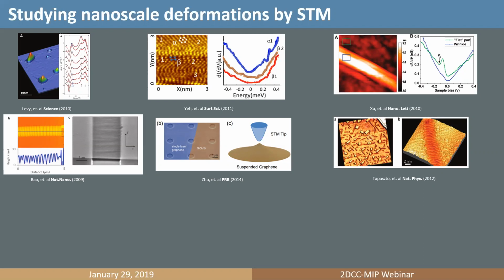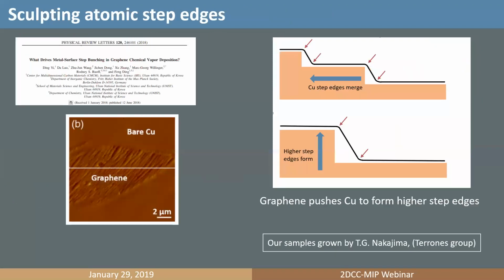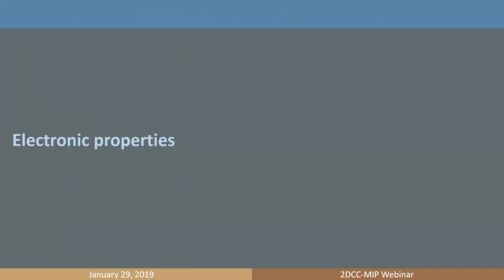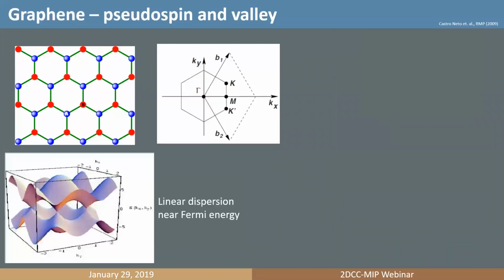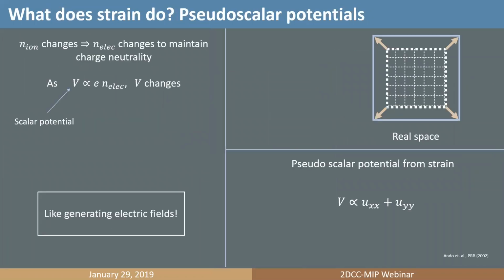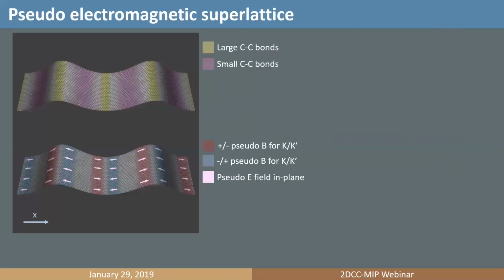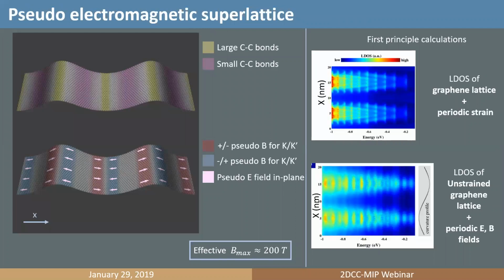Yes. We have a question online. How might one actually use these localized ribbons of pseudospin in a device? That is a great question. One thing is, if you can have this for a long enough ribbon, then you can create a valley filter where only K momentums travel in one direction and K prime momentum travels in another direction. That's like a valley filter, and that's like a topological insulator because they cannot scatter back.